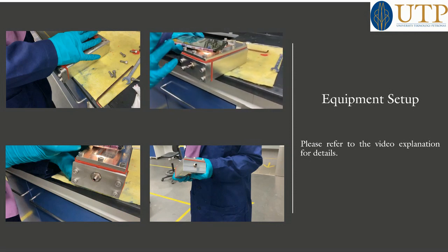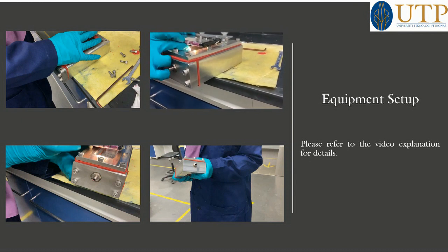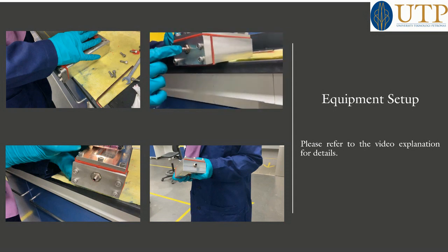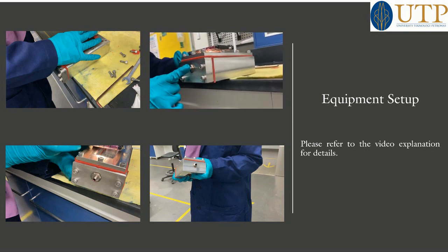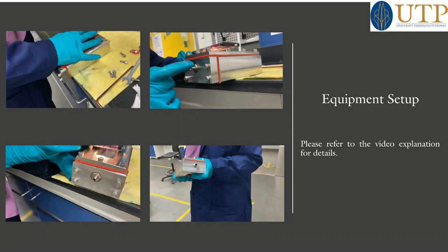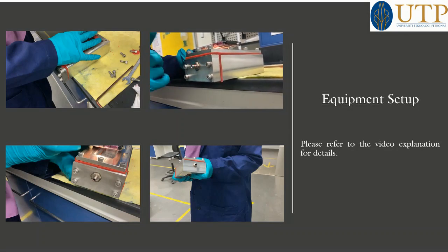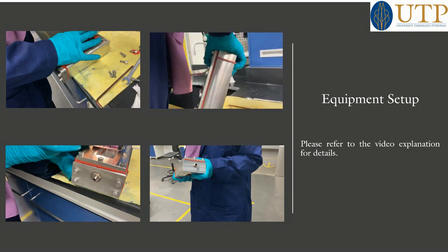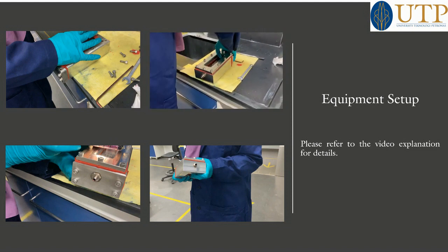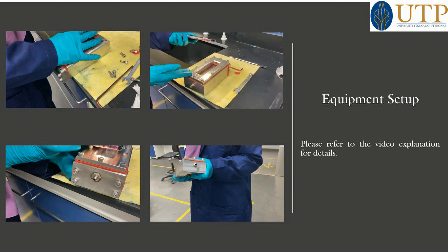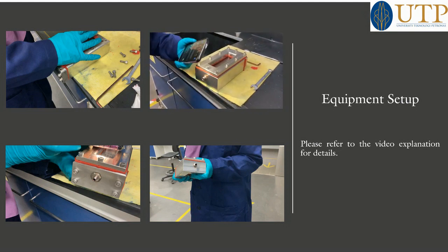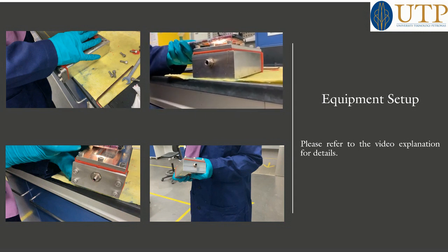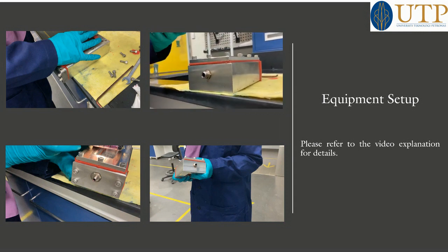If you give some light through this, you can see from this inlet that there is no blockage. That means no gasket blocked it. If you can see only the glasses, that means there is no blockage in the inlet. Then we will check it with our outlet also, because this is the most important thing. If there is any blockage, then no fluid will come. And like this, okay, there is not a lot of blockage, it's okay.